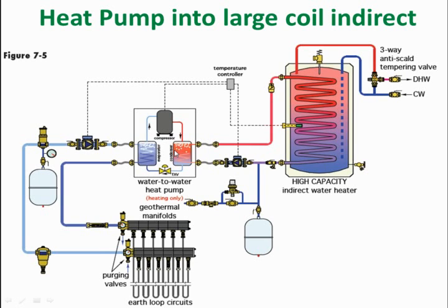Large diameter, so you'd be able to take the output of this heat pump here and pipe it into this tank via the coils instead of going into the water. Now you can pull off either your domestic load, or this could be a heating load coming off the capacity, the water that's in the tank instead of the coil. So that's just another way that you could use a tank, if you have a tank that has the ability to take that kind of flow rate.